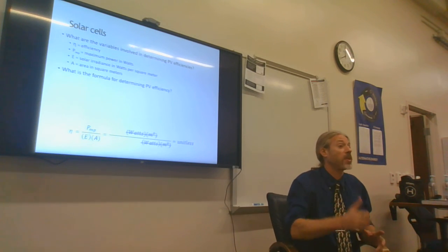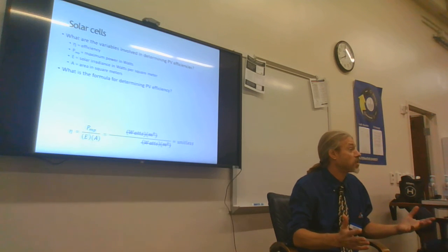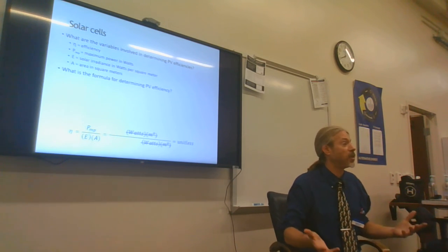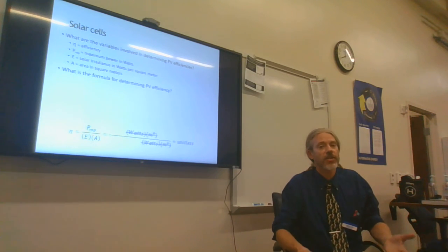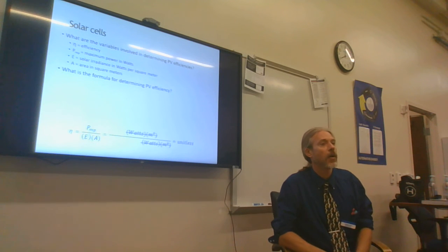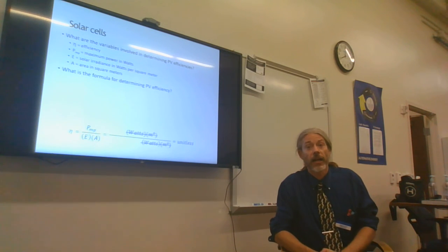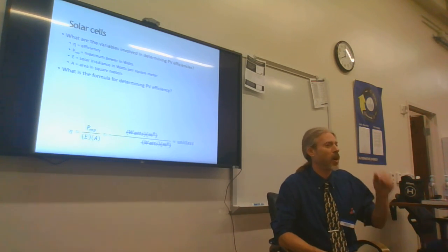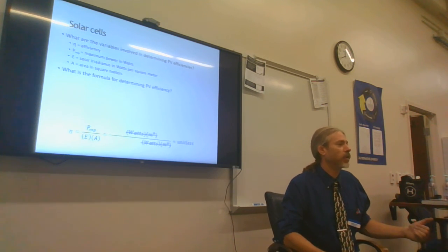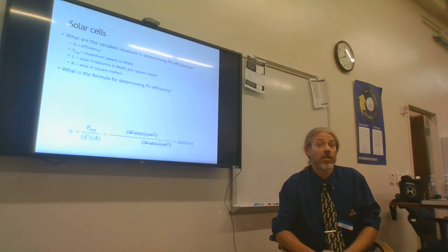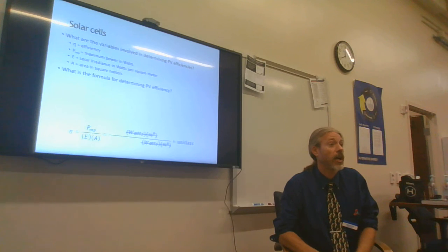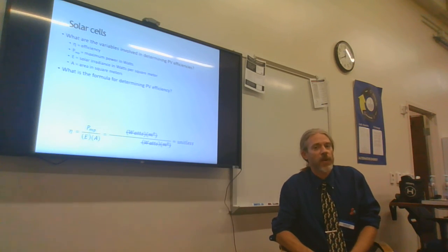When in doubt, just go with 20%. 20% efficiency is pretty standard. Like, hey, I don't know what panels I'm going to use, so I can't do this calculation. Yes, you can. Use a standard 20% efficiency for rule of thumb. Monocrystalline panels will be a little higher than that. Polycrystalline panels will be almost right at that. And amorphous crystalline panels are going to be below that. But we can still get amorphous crystalline panels up to 16%, 17% efficiency now at the high end. Those can get a little more expensive, but